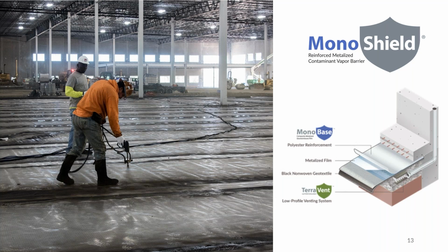The MonoShield system was designed specifically for implementation across slab-on-grade industrial warehouse developments, as you see here. You can see the mono base sheet good and the NitroCore being used to seal off the seams. It's also used for addressing penetrations and termination points around the building perimeter. The mono base layer provides excellent tear and puncture resistance due to that polyester reinforced grid as well as the underside geotextile. And the metallized film and polyethylene components provide that chemical resistance performance necessary for mitigating VOCs, methane, and radon.